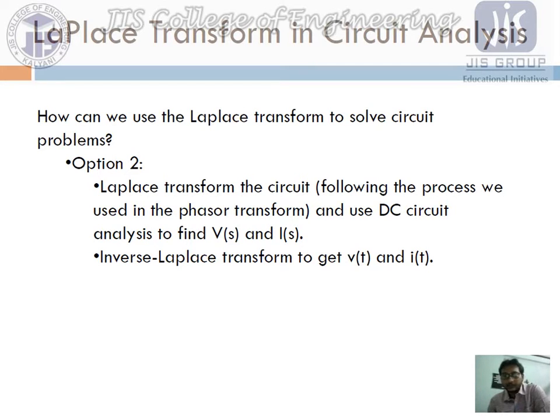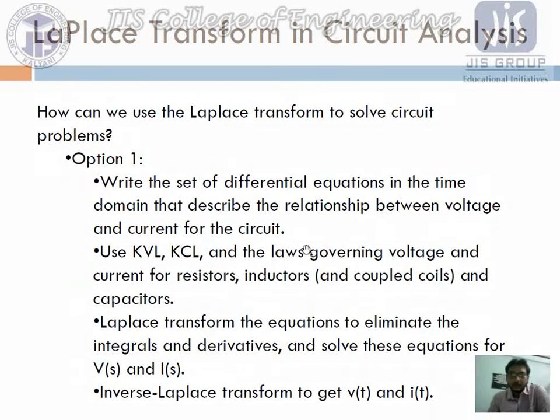So what is the basic difference between option 1 and option 2? The basic difference is that for the previous option, option 1, first of all we write all these differential equations, and then we write the KCL and KVL equations in terms of the time domain. Then we take the Laplace transformation of this time domain equation after finding the KVL or KCL equation, and solve it in the S domain. Then again we do the inverse Laplace operation. This is option 1.